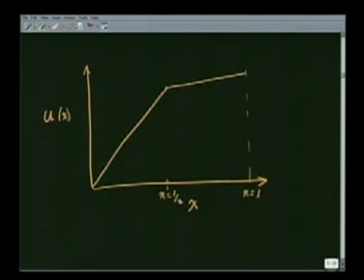If you now take the solution that you have obtained using the Rayleigh-Ritz method, it will do something like this. So this is the exact, and this is the Ritz, 2 term. If you take 3 terms, it will still do this. That is, what you are going to get as a solution is a polynomial.